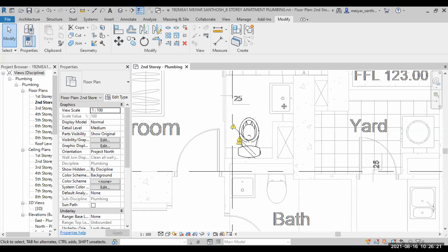Okay, so that means we don't want to use theirs. If theirs are concealed, it doesn't work that way. So that's why in my design I put it inside. If you're lazy, you change, I draw this way. But you give difficulty to people, because the connection in Singapore here, we don't use that way. It's actually from the bottom, right? The flex pipe goes from the bottom. So that means your water pipe will come from here, out this way, then you just connect on the pipe.